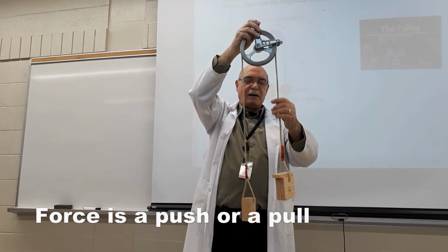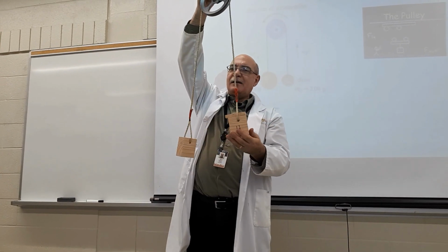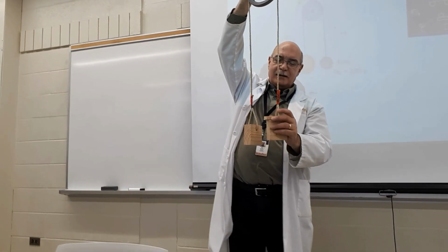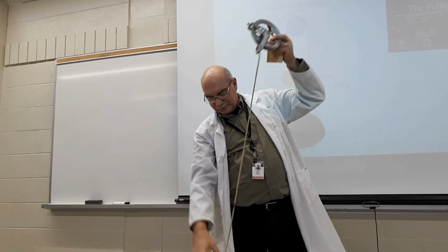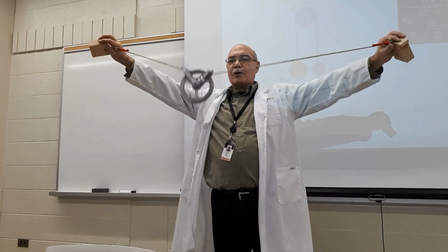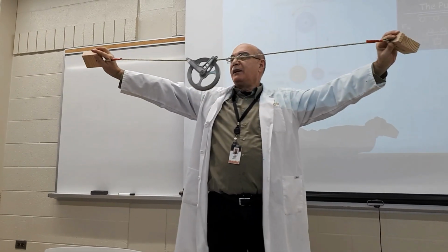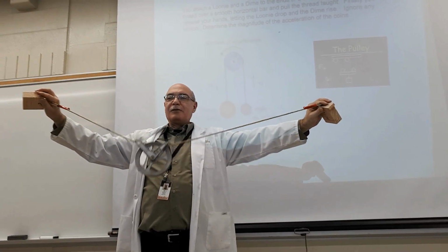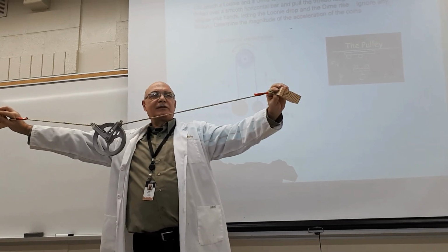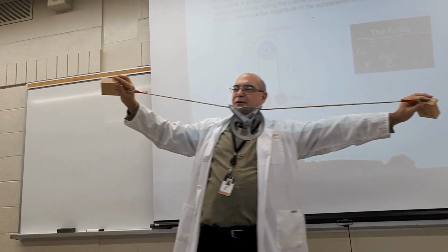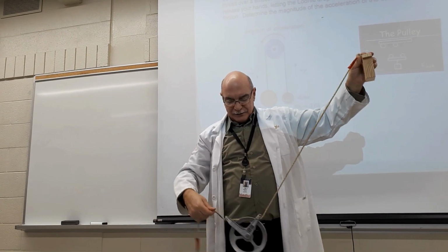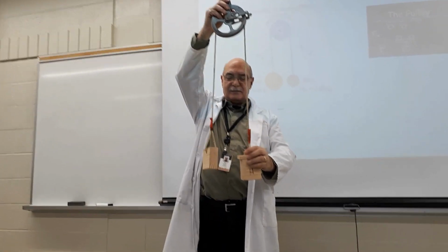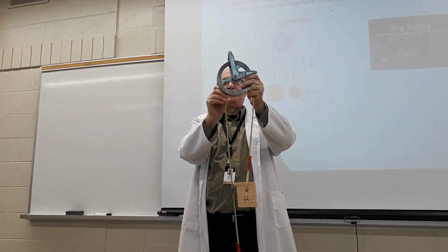Now in order for us to solve our problems, what do we have here? This is a weight force, and I call it weight force for a reason. This is also a weight force. So if that's a force and this is a force, it's the same as doing a tug of war. Somebody's pulling in that direction, another one is pulling in that direction. That is exactly what's happening here with this pulley. Except that it's vertical, but if I were to stretch it out, force that way, force this way, the greater force on that side is going to start moving everything that way. So in order to solve our problem, we're going to stretch it out into the x-axis, take it away from the y-axis. It's the exact same thing.